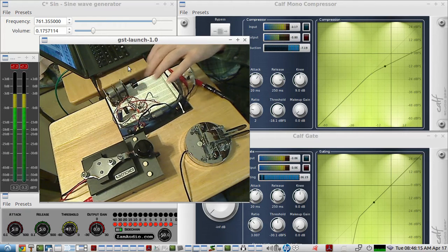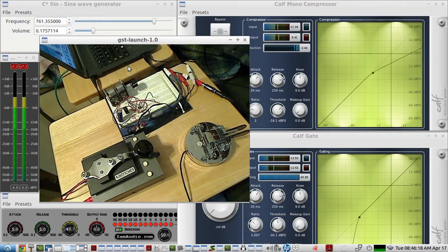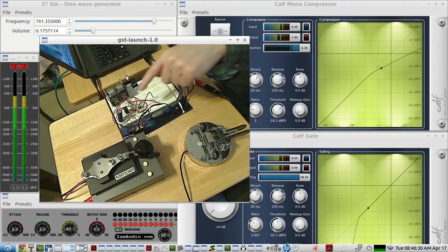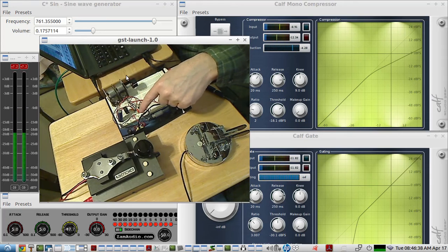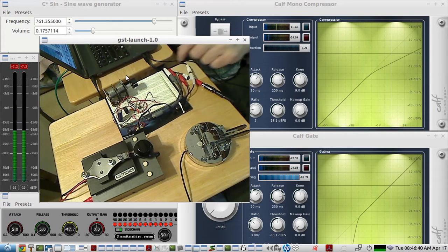This sends out a very harsh and rough sounding tone, but that doesn't matter. You can use any side tone as long as you can key it, and that side tone comes into the left channel of the microphone jack. Make sure you isolate it so that the microphone jack voltage doesn't go back to the keyer. So you need to block it with a capacitor or an isolation transformer. I'm using a capacitor, this orange one you see right there.